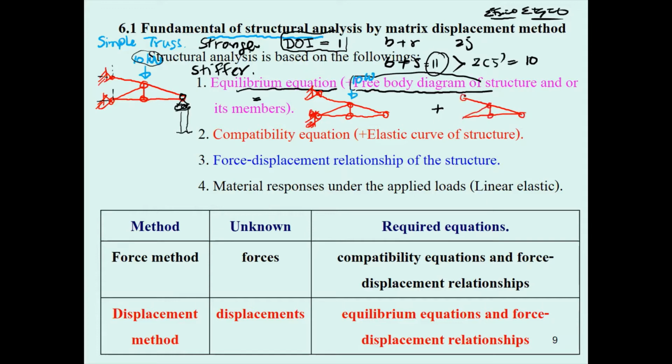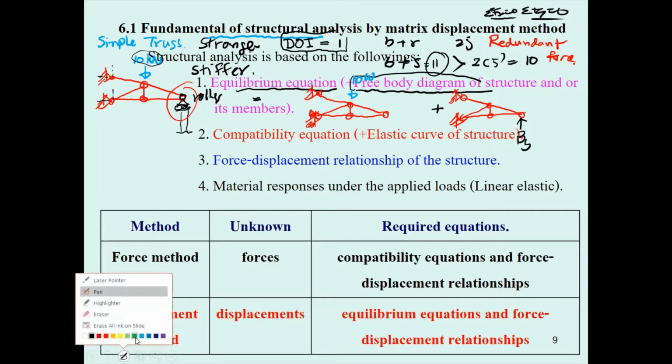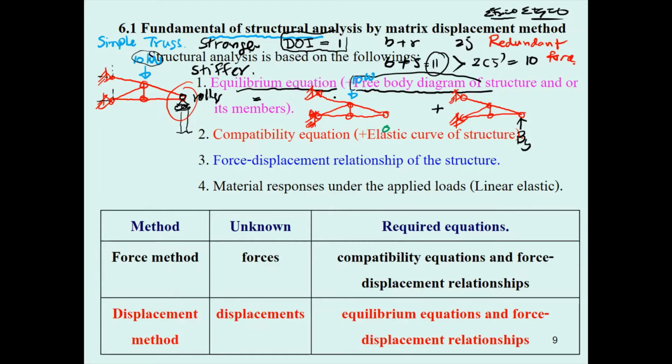Okay, by setting the force that occurs here as the redundant force, you're going to put the B sub y. For example, let's say this point is B, and the reaction due to this roller is the redundant. And now what we have is, under application of the force, the truss must deform into a new shape.